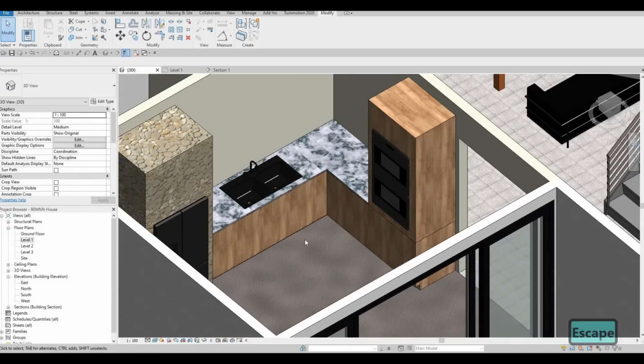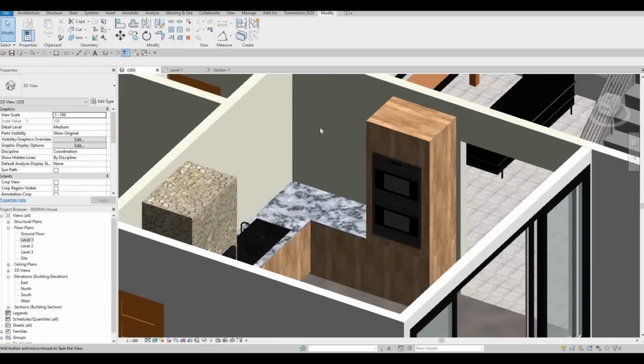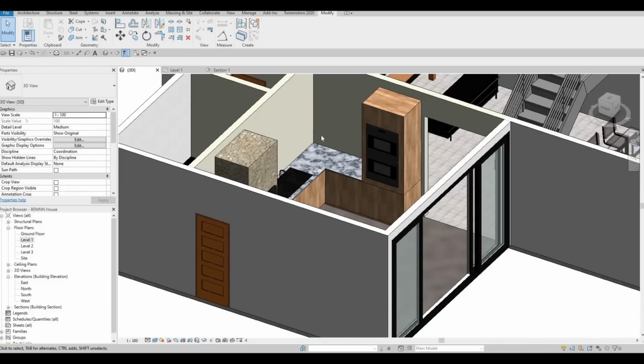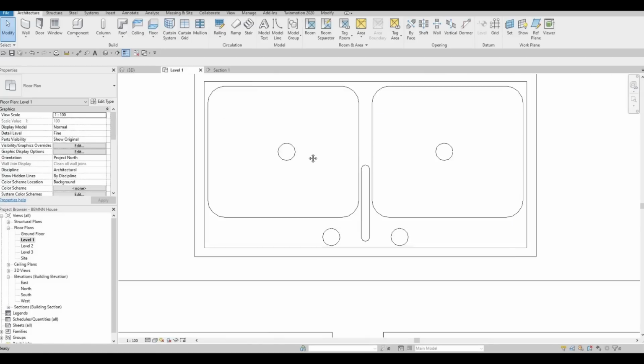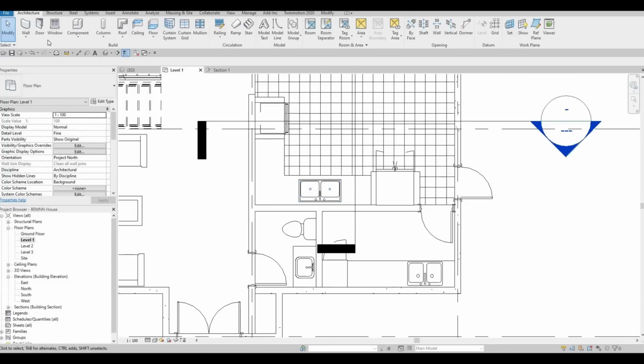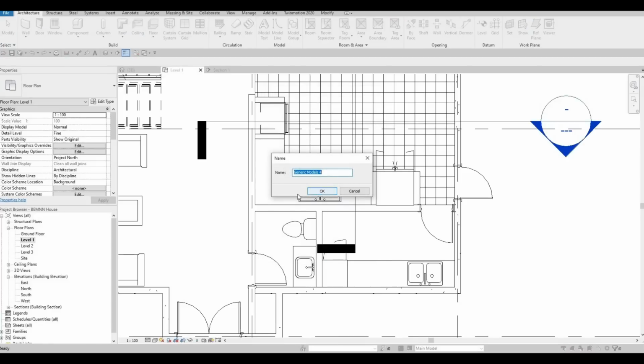Now I just want to do the casing from this side. What we could do is create the case from level 1 and then extrude it in place, and after that we could create the doors for those. So now let's go back to level 1, which is right here, and then we're going to click on model in place and then generic model. Press OK.